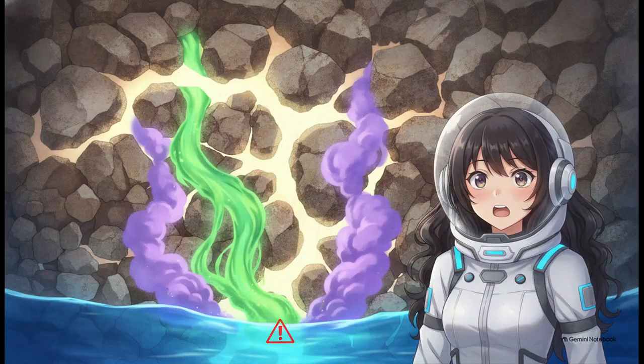The movement of that toxic leachate and dangerous landfill gases like methane is totally dictated by the waste's permeability. And permeability relies on porosity, which is just the amount of empty voids per unit volume. For solid waste, porosity usually ranges from 0.40 to 0.67. If an engineer doesn't calculate this accurately, that landfill could literally leak poison straight into the local groundwater.